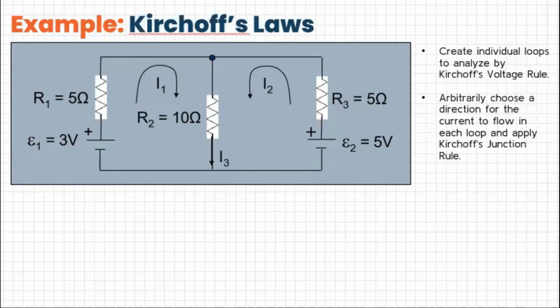So, ang una po natin gagawin dyan, ang technique is to analyze the circuit by demonstrating the loops, okay, the individual loops based from KVL. Okay? So, dito meron tayong dalawang voltage source, E1 and E2. Okay? So, based from conventional current na from positive to negative, so yung una nating loop, I1, okay? Ito yung direction niya. Yung second loop naman natin, since positive to negative, kabaligtaran po nung isa, or opposite nung isa.